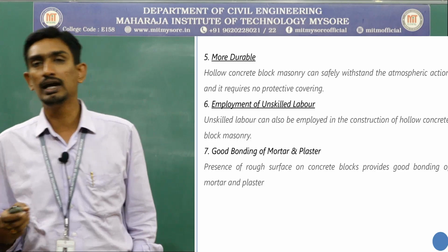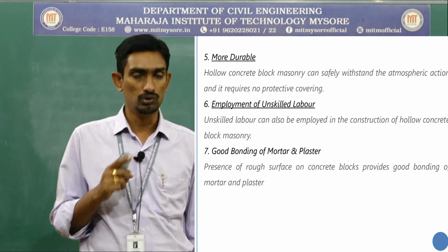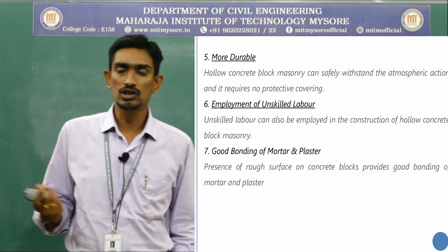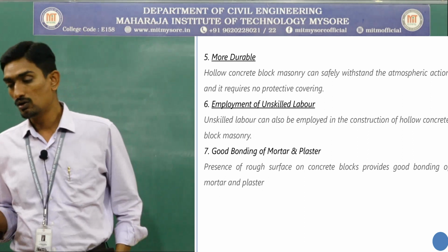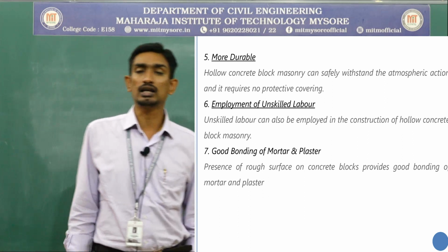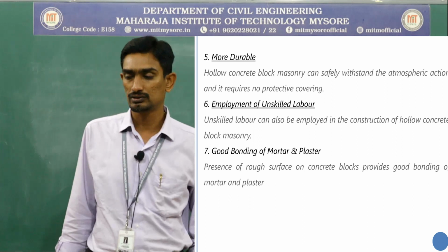Next, more durable. The durability is very high compared to burnt clay bricks, laterite blocks, and stones, because the compressive strength is very high, hence the durability is also very high. Employment of unskilled labor: no skilled labor is required. You can train them very fast and you can prepare the blocks.